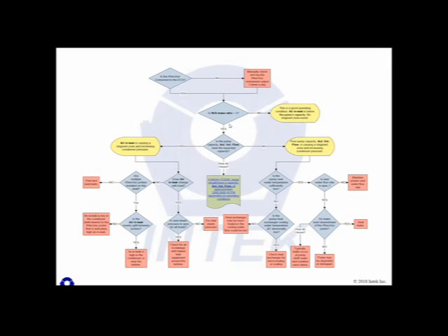The next thing is, if it's yes, if it's less than 3, is the actual cubic feet per minute, the ACFM, as expected? You know, is it in the 1,000 or 1,500 CFM? That's where most vacuum pumps are kind of rated, and it changes from time to time. But for my case studies, if you're over 1,200 ACFM, you're good. If you're less than that, you probably got a problem. We can help you figure that out if you've got your vacuum equipment manuals. But anyway, 1,200 ACFM is a good value.